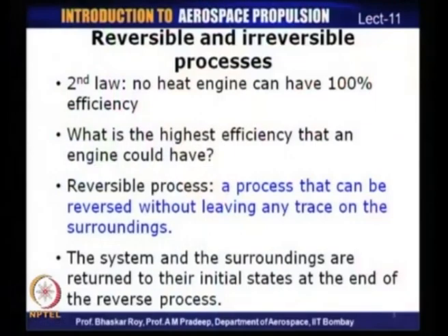If we have to find out the highest efficiency possible for a given cyclic device or a heat engine, we need to define what are known as reversible processes. A reversible process is one which can be reversed without leaving any trace on the surroundings.